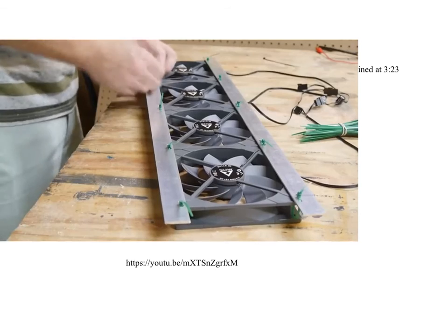The day of its failure, the Tacoma Narrows Bridge did experience resonance from vortex shedding. You can see this in the vertical undulations for which the bridge was famous. But this resonance isn't why it failed. About 45 minutes before failure, a different kind of oscillation started.